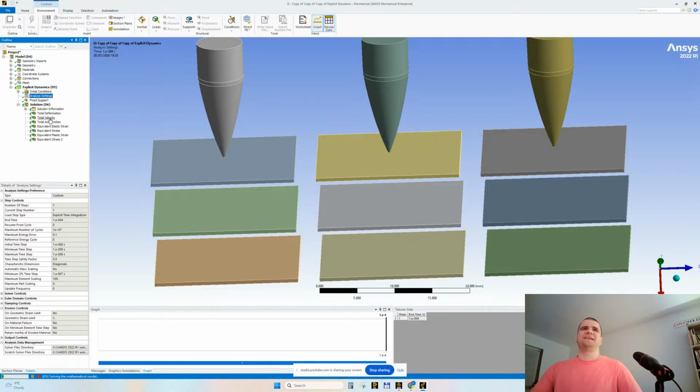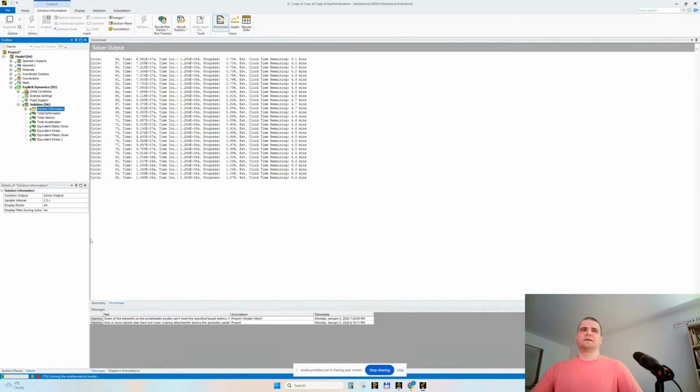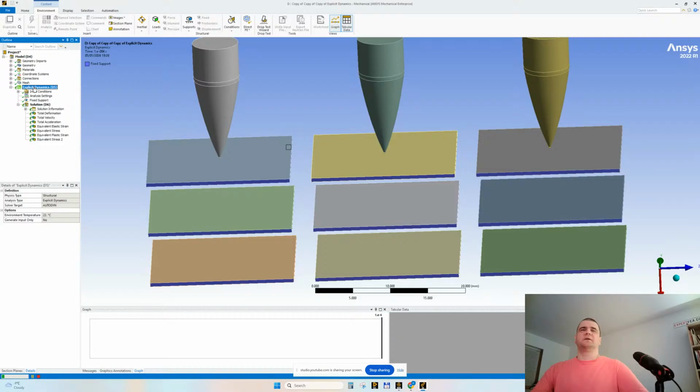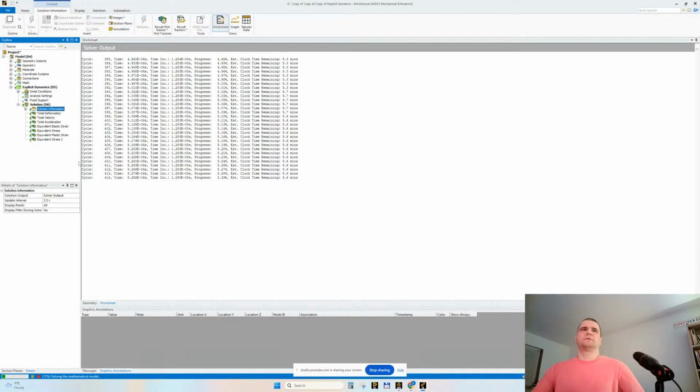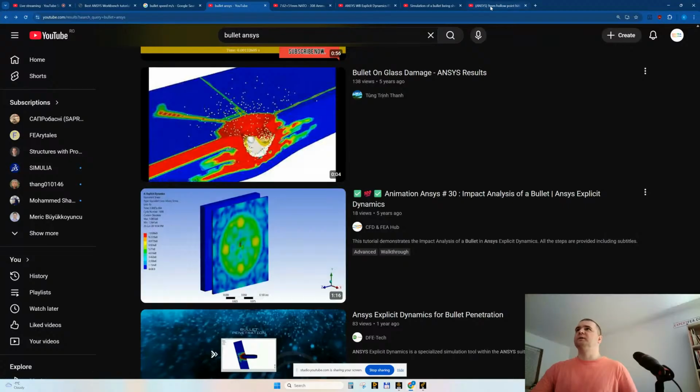The mass scaling itself didn't work because we don't have elastic alloys. The mass scaling would have worked if I kept these plates linear, the default aluminum alloy. But the mass scaling does not do much or almost anything because there are no linear materials.